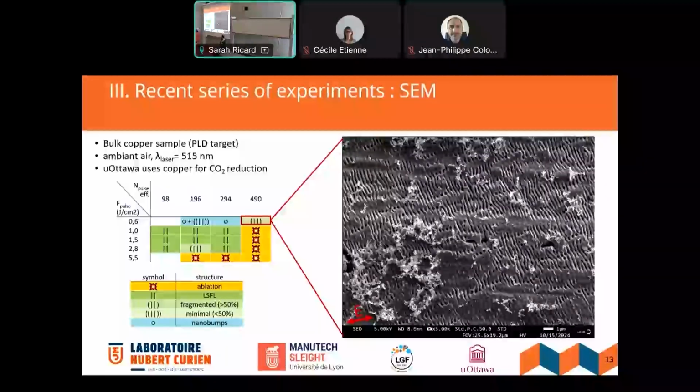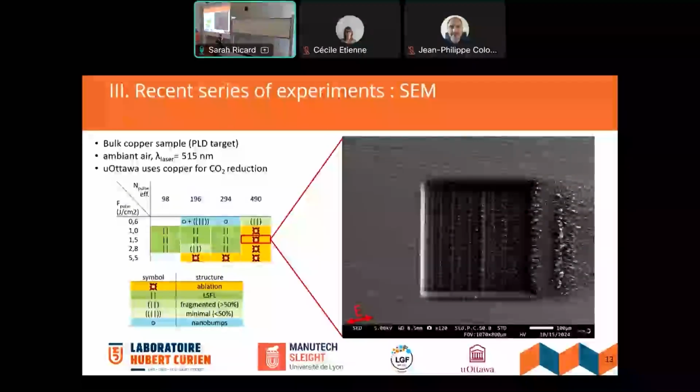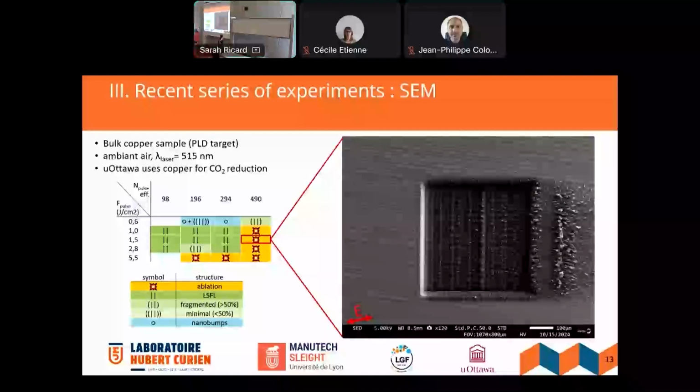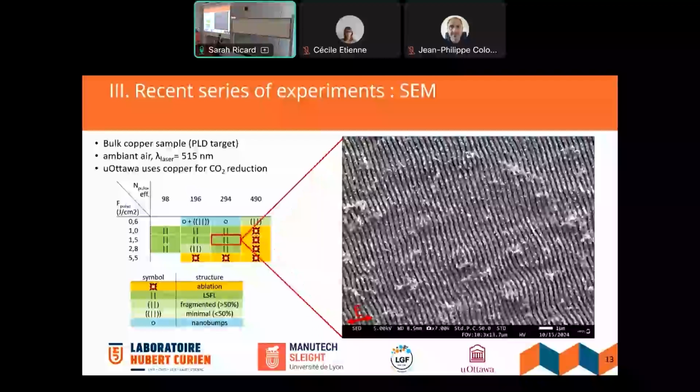When you increase the fluence and the number of pulses, you get into the interesting area, which is ablation. So yeah, when you hit really hard, it's not really interesting. But when you get the right parameters, so the right number of pulses for the right fluence and the right spacing between pulses, you get quite nice looking ellipses. Those are not the cleanest ones we've got, but I wanted to use the same sample.